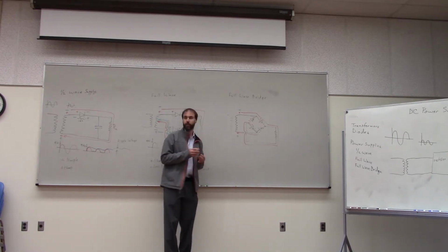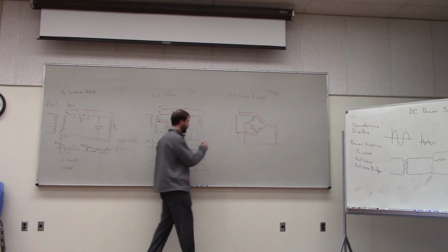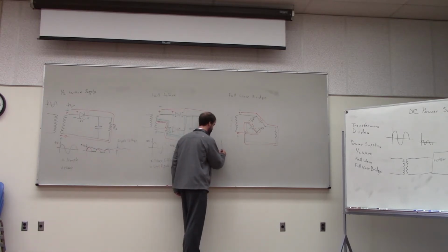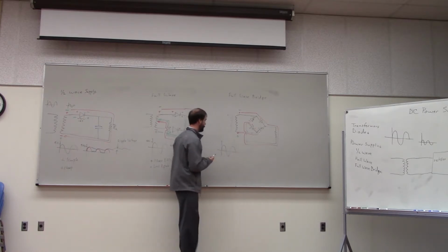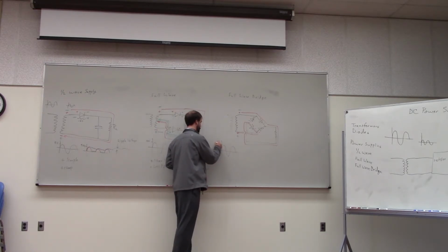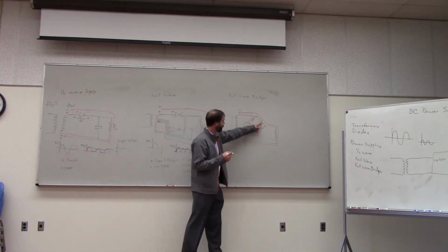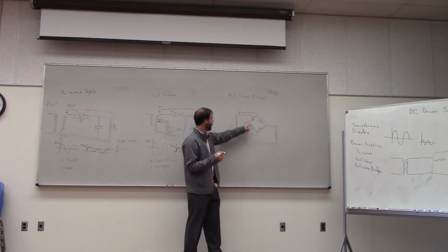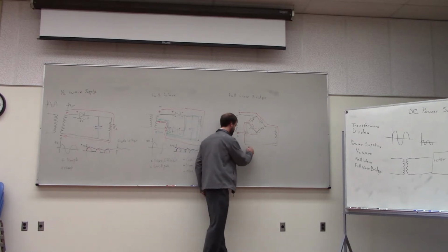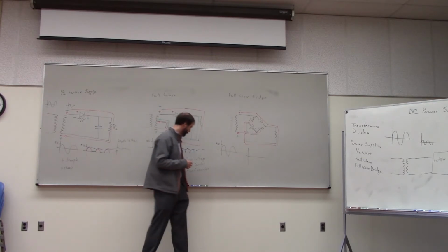So there were two diodes outside? Yeah, we have two diode drops in this one. Exactly. So we start off with 10 volts peak again. And like you mentioned, we lose one diode drop there and then another one there. So we lose a total of how much voltage? 1.2 volts, exactly.